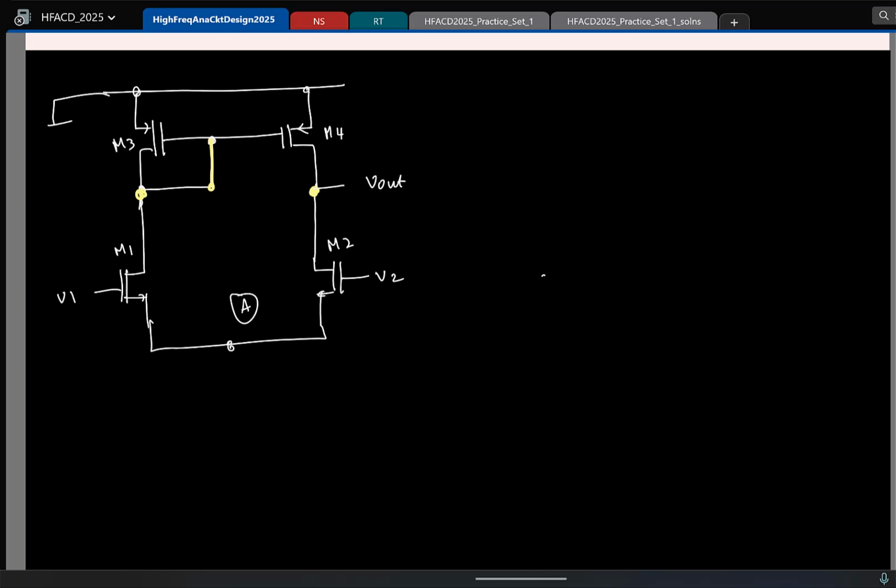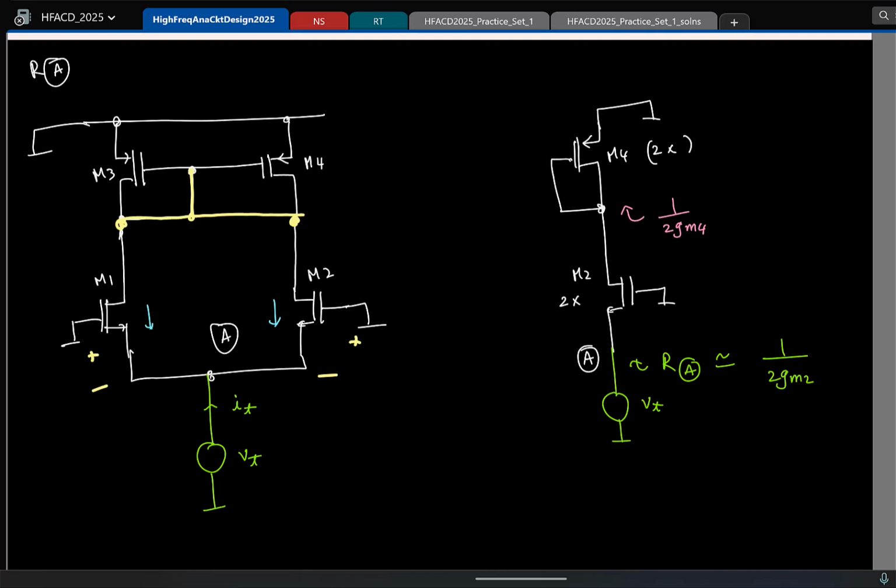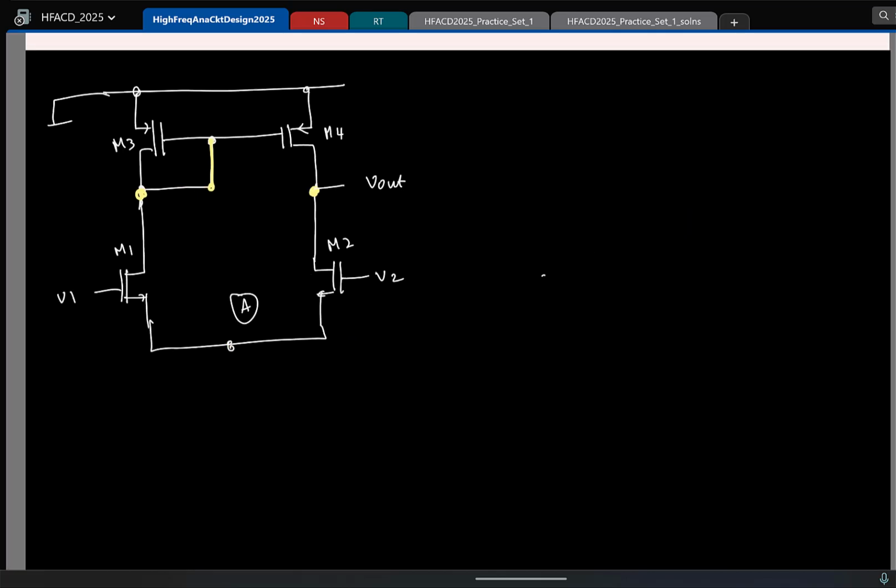But let us say if this was a symmetric circuit like this, what would have been the approach you would have taken to simplify the calculation? The common mode and differential mode half circuit. So here we didn't venture into that approach because of this asymmetry. But now we just made the observation that when will this become symmetric? For common mode inputs, this is symmetric, right? So at least that part is clear.